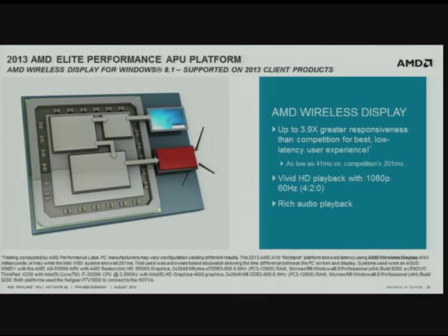So AMD wireless display, the idea here is that if you have a certain thing being streamed on the internal display, for example, on an eDP display on a laptop, you can actually stream that same signal over to a compatible monitor wirelessly. So this is the display controller engine here. This is the display PHY, which is driving the monitor here. But the same thing can be given to the VCE video encoder. And then this engine encodes it. Then that signal can be transferred wirelessly. So we have made additional efficiency improvements for AMD wireless display on Richland.